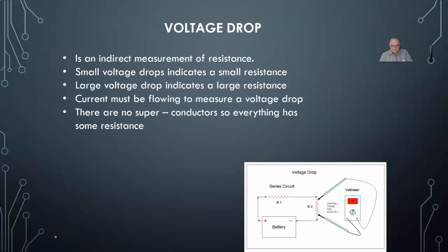And again, since we have a high resistance right there, we should have a high voltage drop. But if you're measuring a wire, you should have a very small voltage drop. So it doesn't matter whether it has 2 ohms or 20 ohms. If it's going through a wire, you should never have more than a 200 millivolt drop as you measure across a wire.